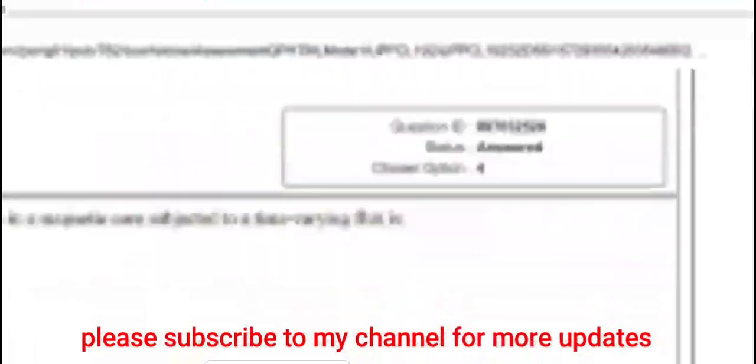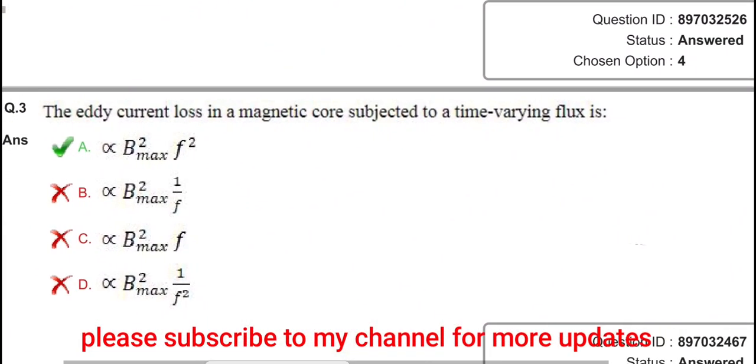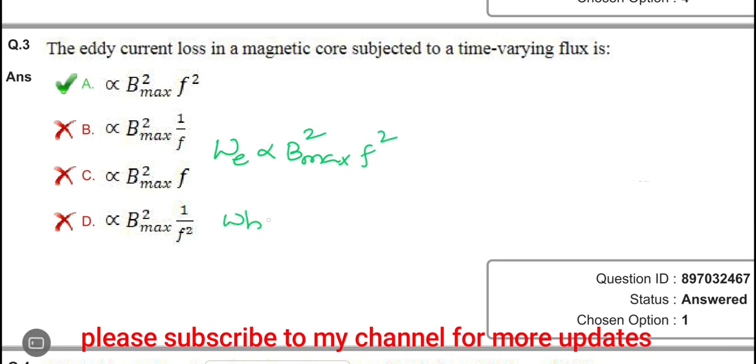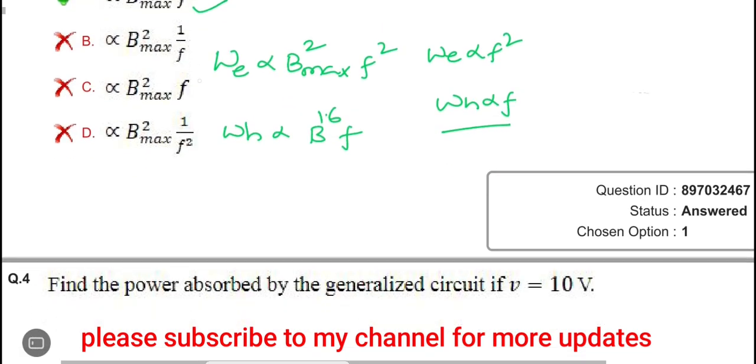We'll go to the next question here. Now the eddy current losses in a magnetic core subjected to time varying flux are given by Steinmetz's equation: We is proportional to B max square into F square. Suppose they ask about hysteresis losses, it is proportional to B max to the power of 1.6 into F. From this, the conclusion is that eddy current loss is proportional to frequency square, and hysteresis loss is proportional to frequency. So one is the right option for this answer.